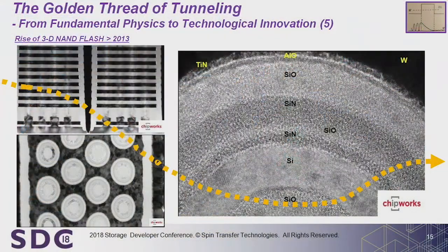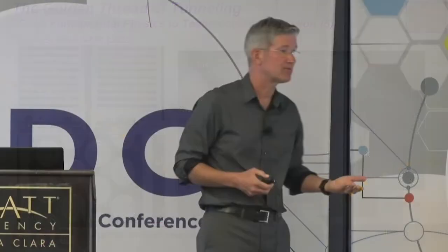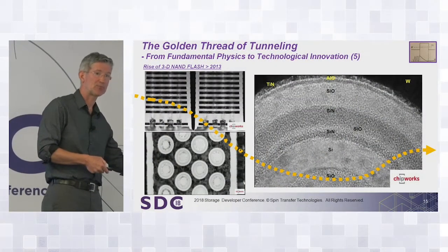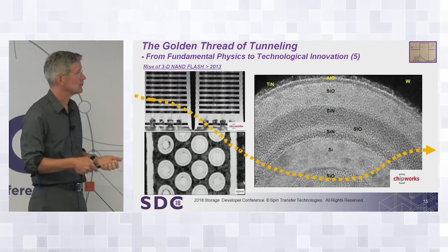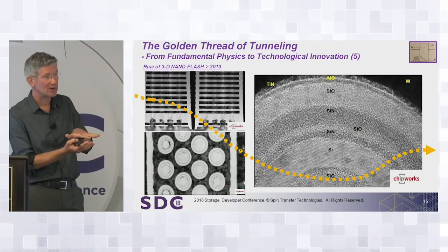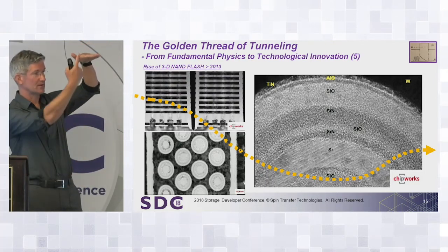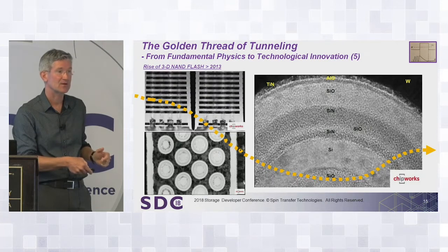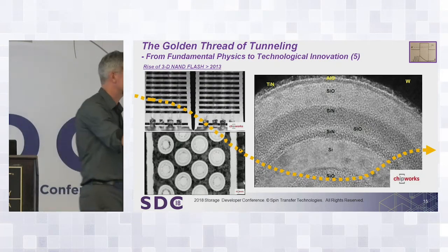The other thing that's interesting about this is all other NAND, all other flash and so on, was built in the substrate. So the substrate is monocrystalline silicon. This was then polycrystalline. This is polycrystalline silicon. And when you go from one to the other, you limit the mobility of the electrons in that material. So the amount of current out of this is much lower than if you build it in the monocrystalline substrate. So one of the challenges that the 3D NAND folks have to deal with is that to increase capacities, they have to lengthen the string. So the string is one big long resistor. So you can imagine a big long resistor combined with much lower mobilities of the electrons in that resistor lead to much lower currents. So they have to deal with sensing that current.